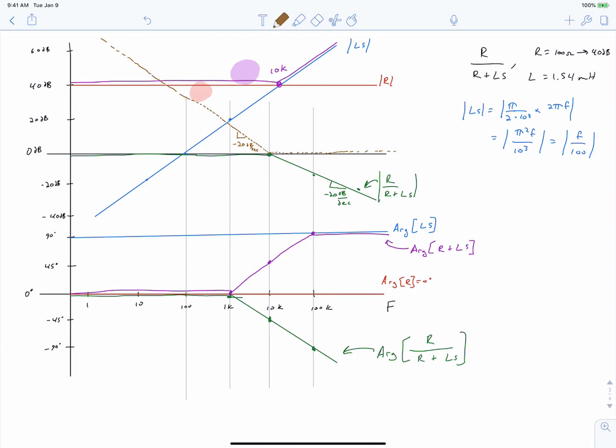And if we had this transfer function, the brown line for our regulator, added to the transfer function for the power stage, the green line, you can see that we'd have the performance that we'd want. We'd have a high gain at low frequencies. We'd cross over the 0 decibel point at negative 20 decibels per decade. And so we'd follow the design guidelines that we talked about in our last lecture. We'd also end up with presumably a good phase margin as well.